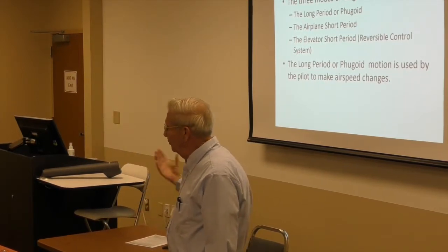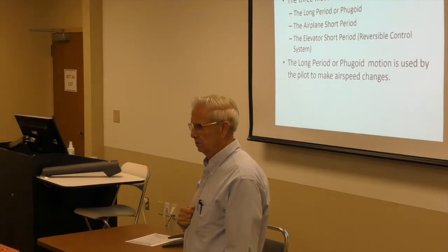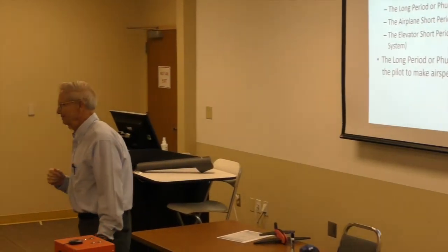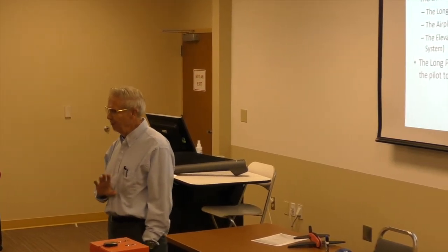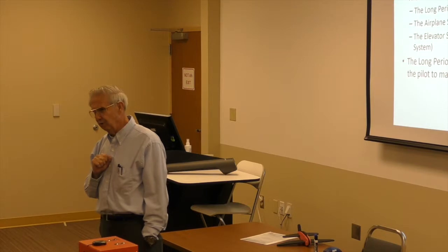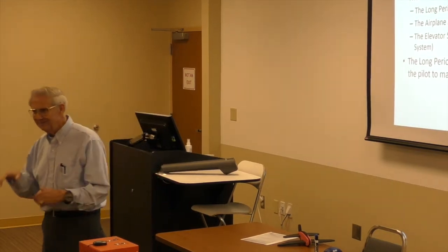Fine, nobody had any problem with the short period dynamics, and the Air Force bought the airplane. And the Air Force intended to use it for low level. Well, all of a sudden, people were sticking airplanes in the ground. Because the short period motion, which is about at the human reaction time, was not so good on the F-4. And particularly the pilot would tend to get in the loop because its frequency was right at his. And so they did a big investigation as to what's going on. Nobody, prior to that time, worried much about the short period. Okay? Because it was always heavily damped. Well, on those airplanes, it wasn't so heavily damped.